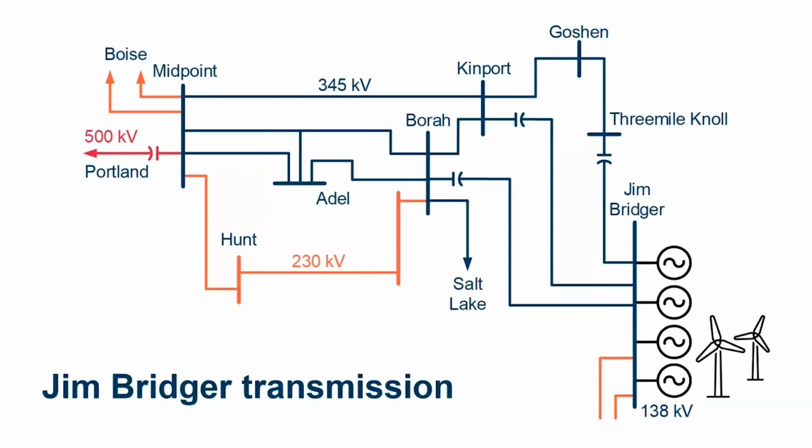Meanwhile, protecting against several known dynamic stability issues such as out-of-step tripping. This is a dual triple modular redundant remedial action scheme utilizing proven substation grade IEC 61131 compatible programmable controllers, protection grade relays, and high-speed IOs.